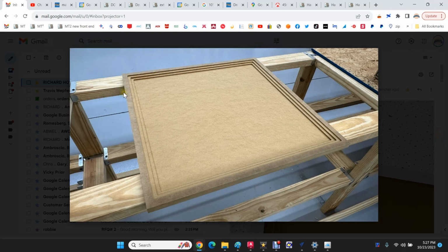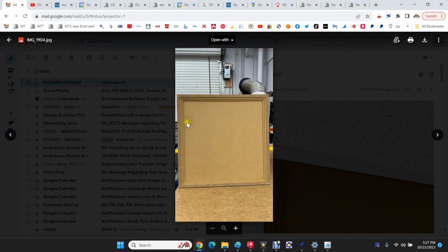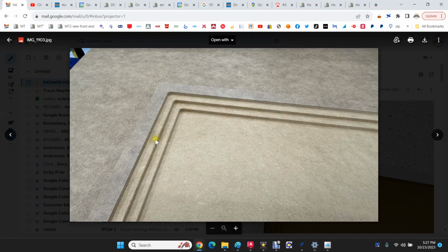So I've got roughly 24 by 24, then I've got 22 by 22, 21 by 21, and then 20 by 20 as I'm calling these three pocketing toolpaths. So what I ended up doing was cutting this 22 by 22, 3/16 deep. This one's 21 by 20. It's not, it's bigger than that, but just for argument's sake, 3/16. So by the time I got to this one and this one, I'm air cutting because of my settings.